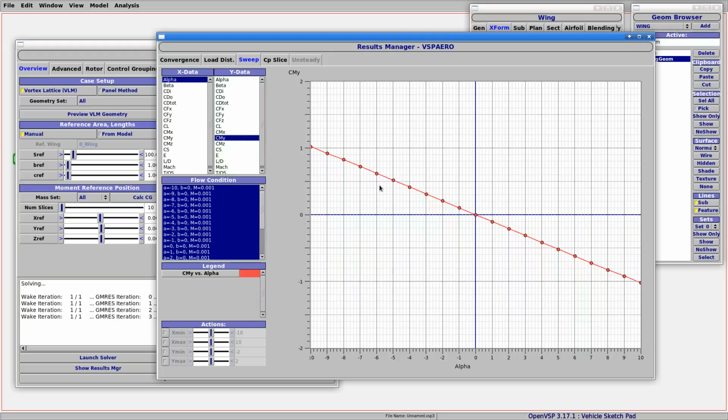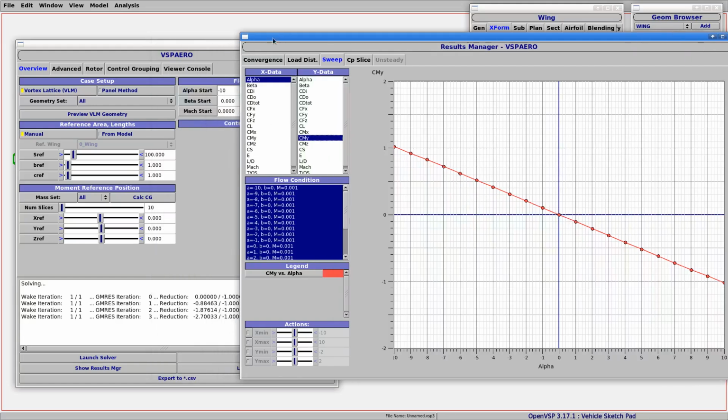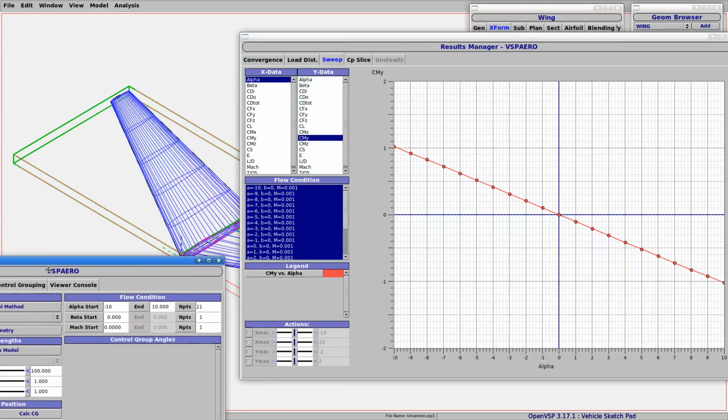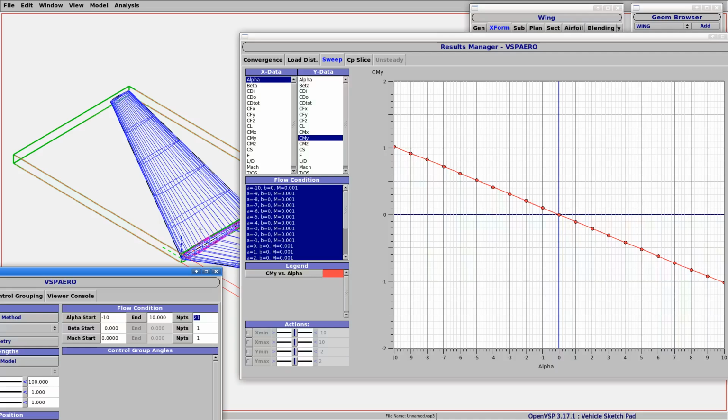And vice versa over here: as the angle of attack goes down, in other words, as the nose of the plane goes down, the natural tendency of this torque caused by the airflow around it will tend to pitch it up again. So it's going to settle on this point here. This is what we talked about just before. And in this case, for this extremely boring wing that we have, it's basically the flat sheet example, so it's going to tend to stabilize at this point here, which is an angle of attack of 0.